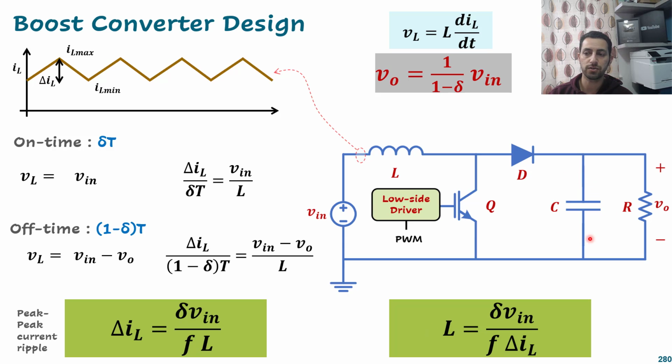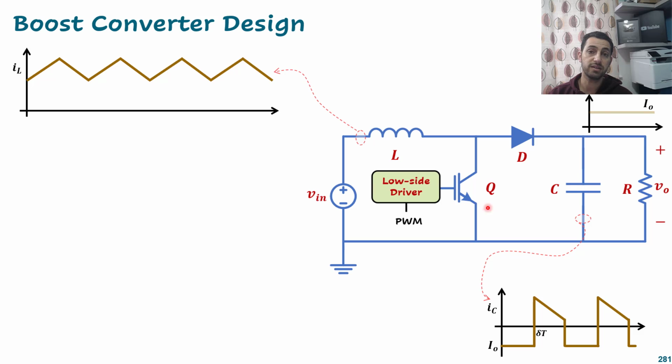But what about the capacitor? Does it have any ripple here? Let's see. If we have that current going through the capacitor here, and that current has this waveform, that means yes, the voltage will change with that current. And how the voltage will change, I think during this portion here, the current is negative, because at that portion here where the switch is on, the output now is relying on the capacitor to give it its charge. So that's why it's discharging that current like that, and that's why we have a negative value.